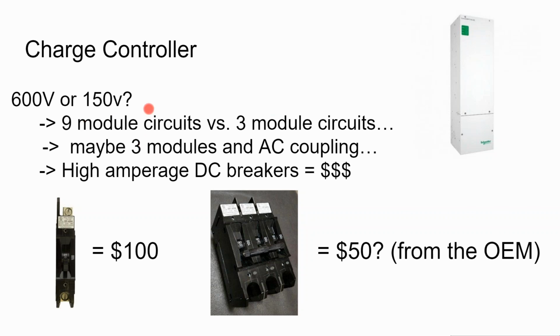And so that's kind of where I come in on, being a big fan of 600 volt charge controllers, is because I like the DC to DC connection. I like doing DC coupling for black starting, not needing the inverter, not needing to worry about reserve capacity in the battery, having it there so that if the client actually bricks their battery, when the sun comes back up, they'll start producing power again. If I'm doing a ground mount that's right next to my house, maybe wiring up all those circuits is not a big deal.